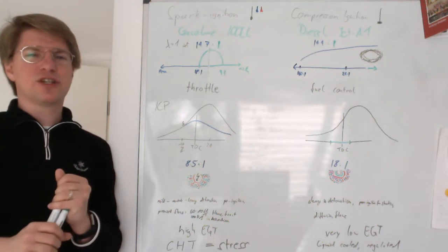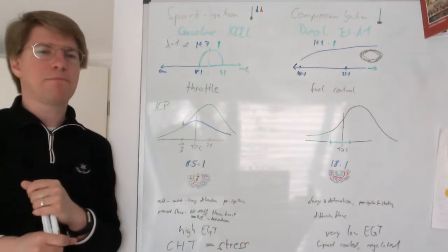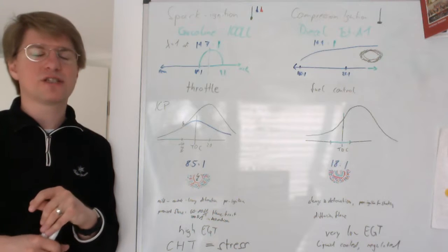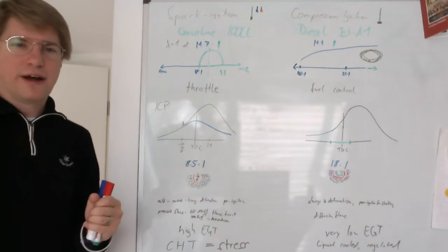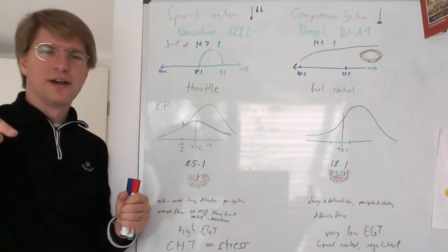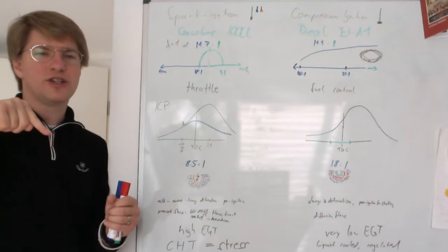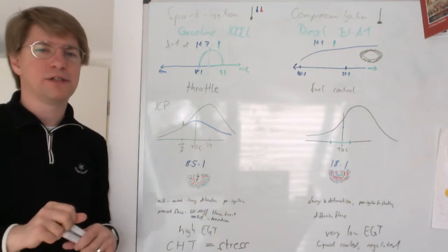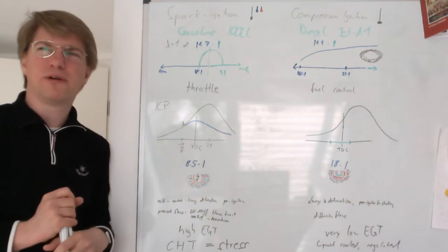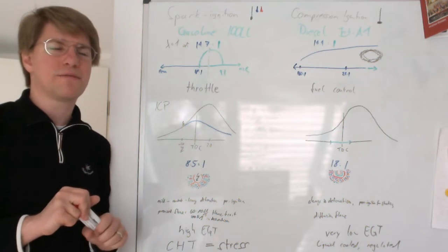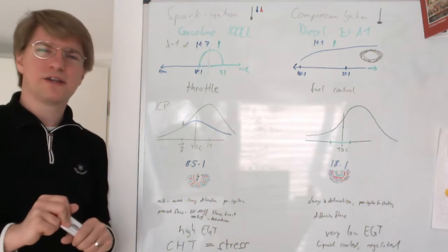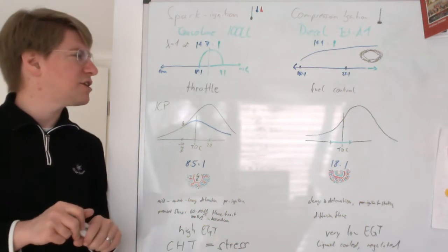With fuel-injected engines, and with aircraft engines we are talking MPI, like for your car, multi-point injection. So fuel injection in aircraft engines almost always is multi-point injection. Not to be confused with direct injection, the fuel is not injected into the cylinder. With fuel injection in aircraft engines, the fuel is injected at the intake port, MPI, multi-point injection. There are a few aircraft engines that have single point injection, although they call it something else. They call it a pressure carburetor. But you don't find these in the general aviation fleet, as far as I'm aware.